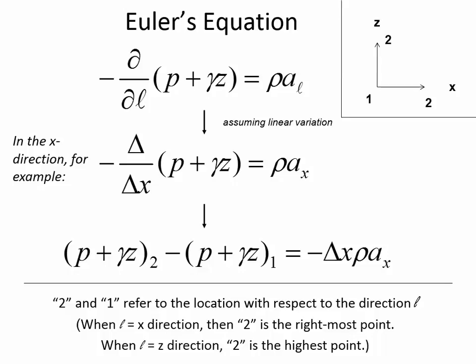The hydrostatic equation is built into this, so that even if there's no additional acceleration beyond ordinary gravity, Euler's equation would still be able to tell you what's the pressure change between 2 points. So we don't have to separately account for this hydrostatic effect. It's built in, the hydrostatic equation and also the effects of movement in whatever direction we're applying this to.